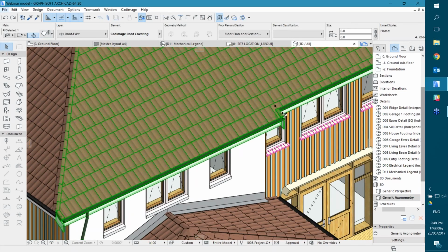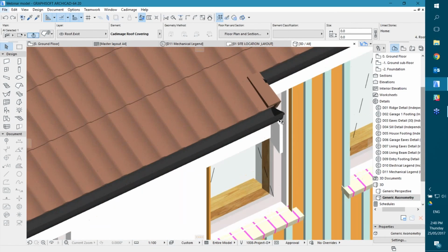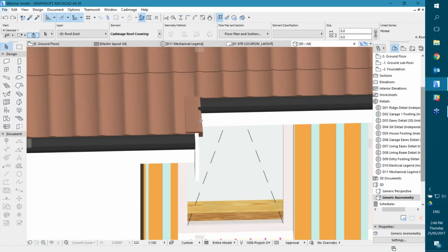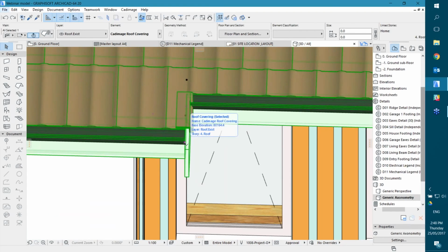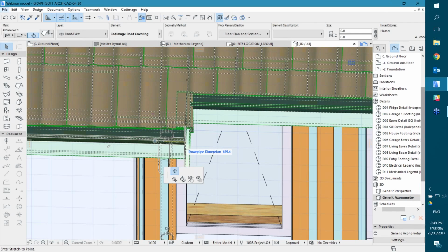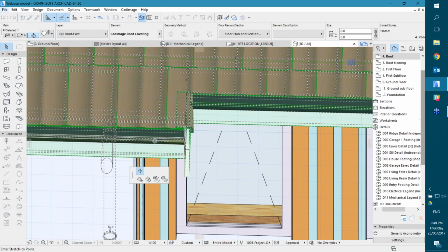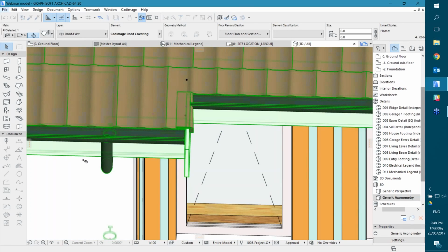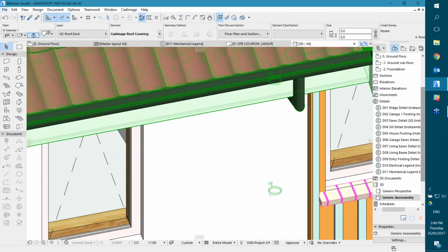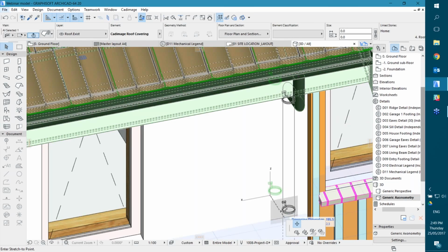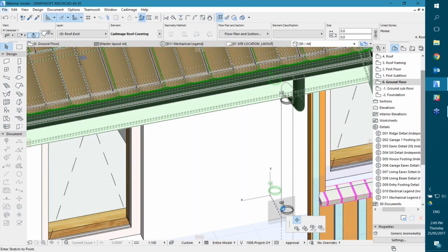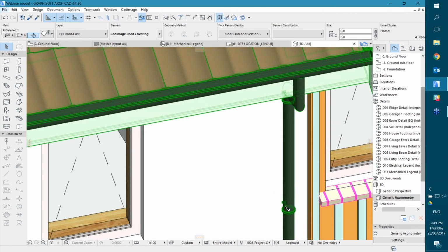So there's a purple hotspot in this gutter here, this one here where my cursor is, and if you drag that out anywhere that is not 0, 0, it will draw a downpipe on there. You can see that there, it's popped through the wall, but we can drag it out easily enough. And again, those settings were set back in the covering dialog that we saw earlier.